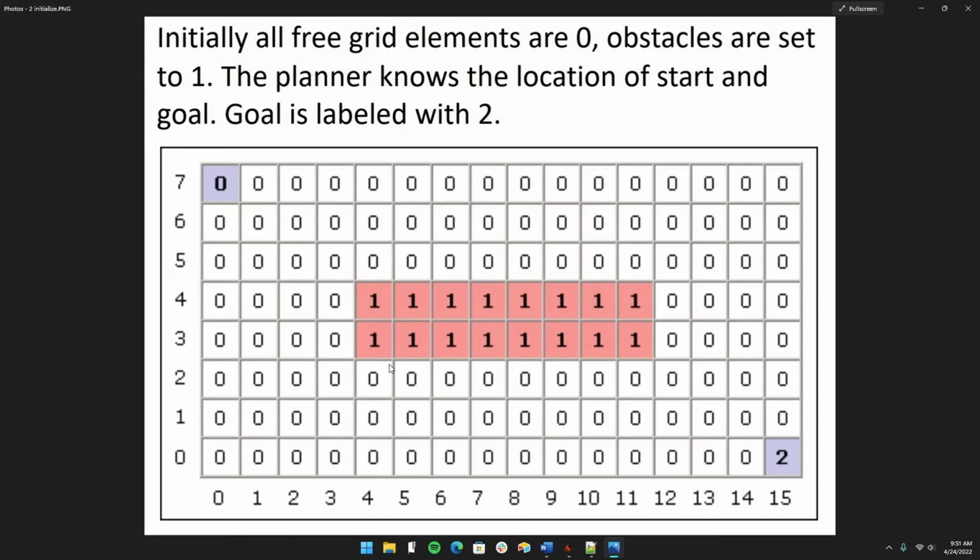Here's how that works. To start the wavefront planner, you set all free space cells on the known map to a value of 0, all obstacles and walls to 1, and the goal cell alone gets the value of 2. They happen to be color-coded as well on these examples, with the free space being white, the obstacles red, and both goal and start cells set to blue.